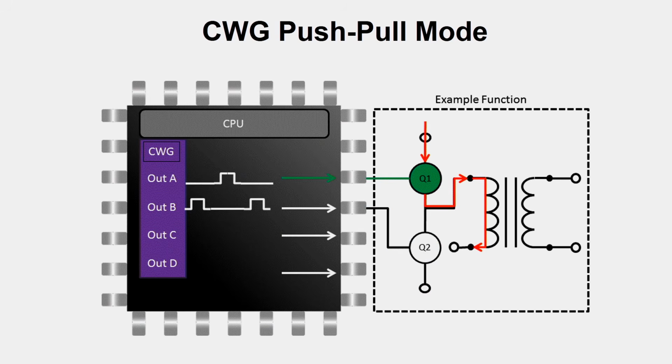This peripheral allows you to take a single PWM source or a single square wave source and run it through this peripheral, and then you've created a complement of that input waveform. So you can see output A is one waveform, and its complement is output B. Basically it's applying customized timing or logic to your waveform input to make this complex waveform output.